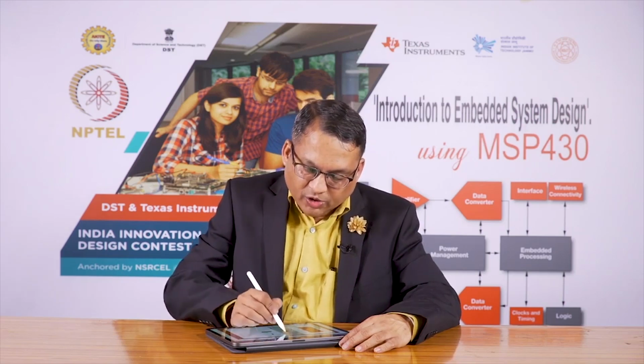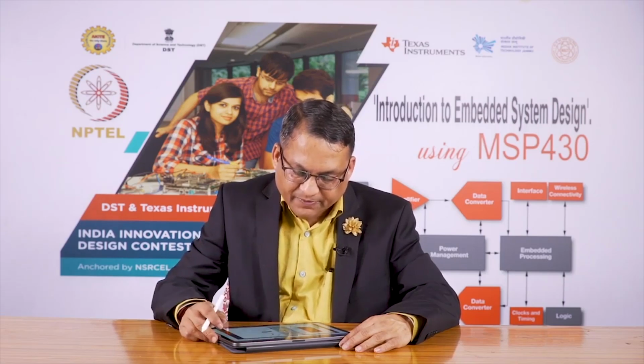Of course, we also connected 2 capacitors here. This is to reduce noise in this case, and then we have this switch here with a pull up resistor, and we also have connected a capacitor here so as to debounce that, although we are doing debounce in the software also. So, let us see what the code looks like.